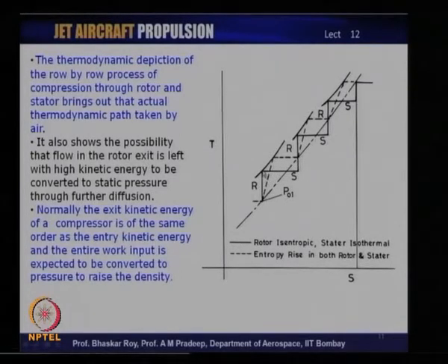It is k equal to gamma, and then k equal to 1, then again k equal to gamma, and then again k equal to 1. So, it is the step by step process by which the compression actually proceeds thermodynamically in the typical TS diagram, if one does a rigorous analysis.